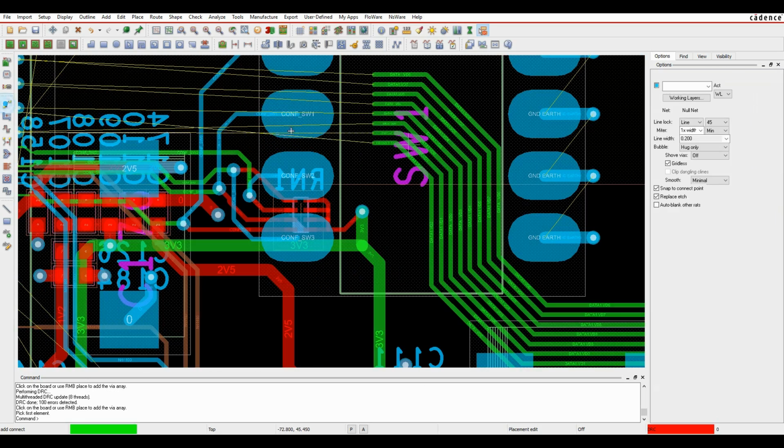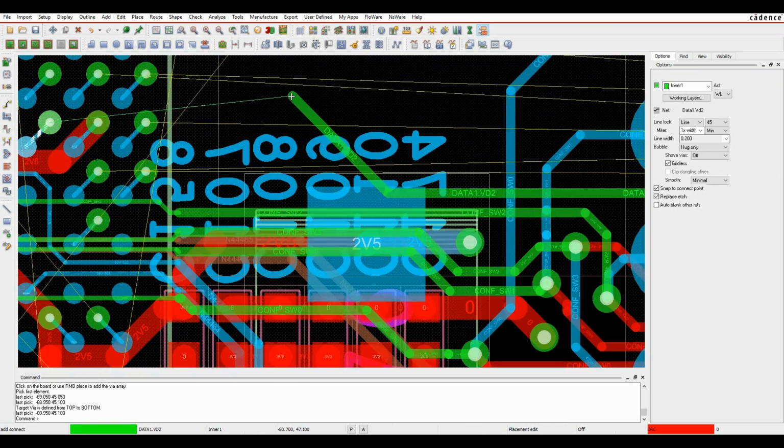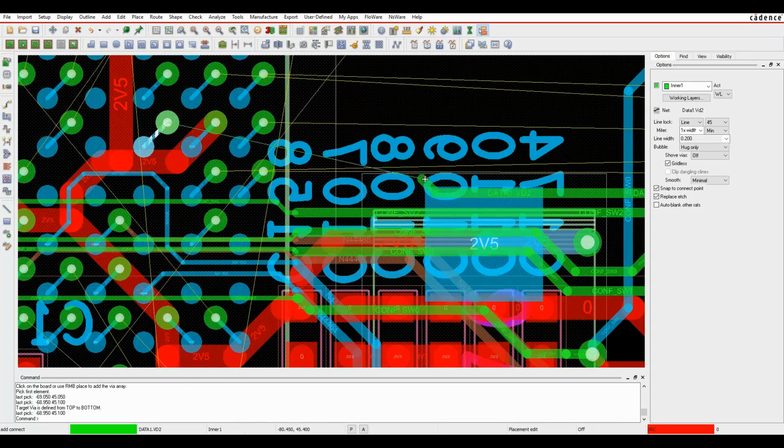I'm now going to route a track, and we're going to take this into a BGA area. So obviously I've got quite a thick default track thickness. When I go into the BGA area, I'm never going to be able to fan out this BGA correctly or escape this BGA correctly based on this track thickness, so I can use something called a constraint region or rules by area. You can see as soon as I enter the BGA, the track automatically necks down to the thickness and to the spacing between the 2 traces to allow me to meet the constraints that I need to get the routing done.